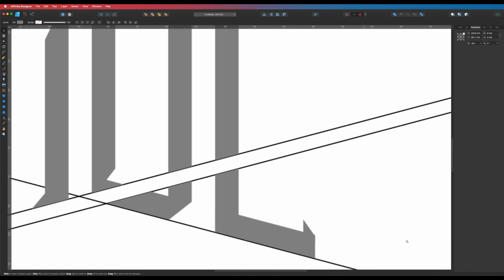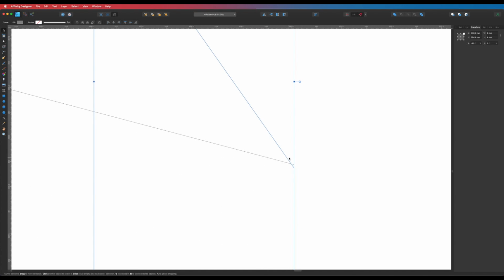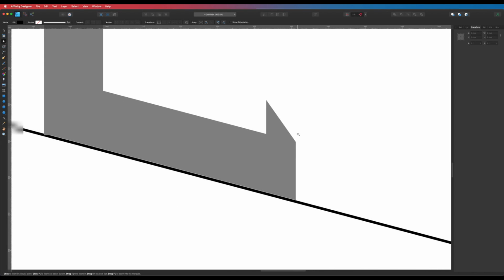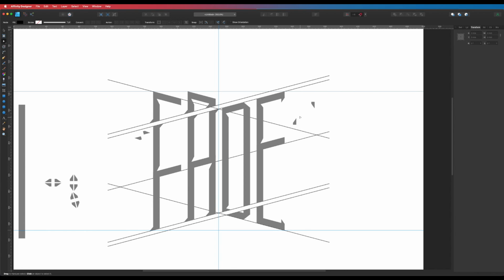Okay, just going to go in here, wireframe again, click your graphic, just get it to that point there so we don't get that little piece sticking out. Okay, get your node, select your graphic, get your node, just drag it up, drag it back in, snap it there. Then we know we're not going to get a funny little divot or anything over there. That's perfect. And then our E, which way do we want the E? I think our E's got to face down like the top piece.